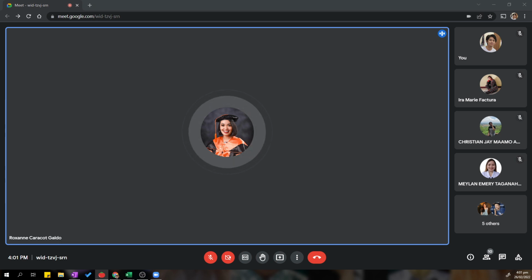So hopefully in your laboratory, since it is a co-requisite, you will be able to cover this test, because it is one of the most simple tests in materials testing. You are only going to need the VICAT needle apparatus, the cement, and a timer, and you just record the penetration with respect to time. Okay, so do you have any questions?